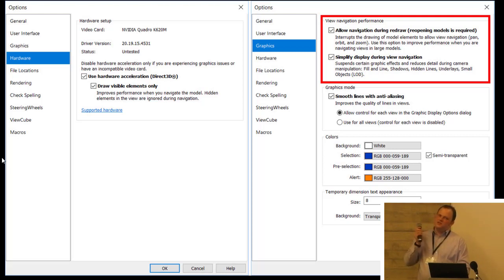Just a little side, it's not a tip actually, but one thing that I've seen, I'm trying to tell people so they don't fall into the same trap: embedding links into links. I've seen people with Revit models, increasingly as we're getting more and more complicated Revit models, relying on links to compartmentalize their information, separate it down and so forth. If you start to bring in lots of links into Revit, and if you bring links into those links, i.e. you have a second layer of links, be prepared for the performance of Revit to crash horribly. Again, I've got one person at the moment with a 500 megabyte model, and it's taking 40 minutes to open.